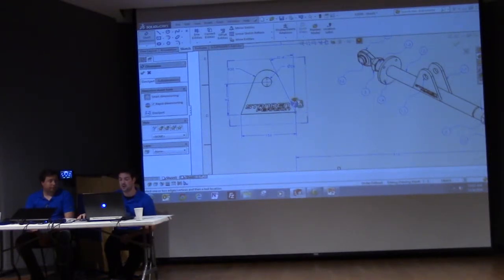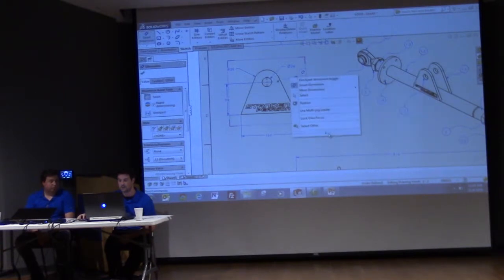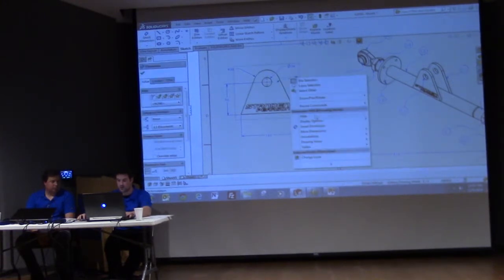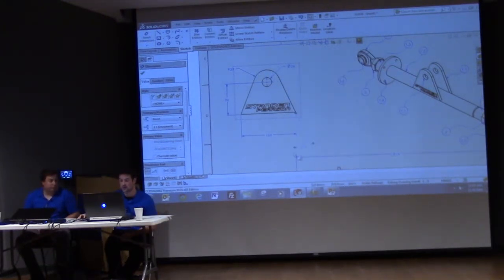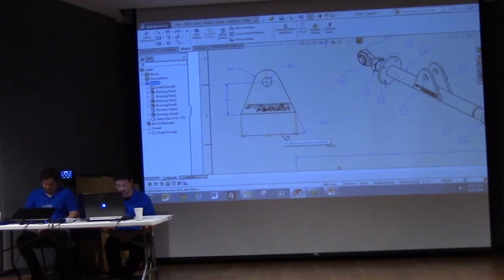If I choose this one here, you can see we can, of course, apply the angle to anything based on that reference. I can select that quadrant, and we also have the ability to show the explementary angle, or we can look at the vertically opposite angle. The explementary would be 360 minus the 22.4, or if we do vertically opposite, it drops it down on this end, and then of course we can line that up with the dimension that we already have there.